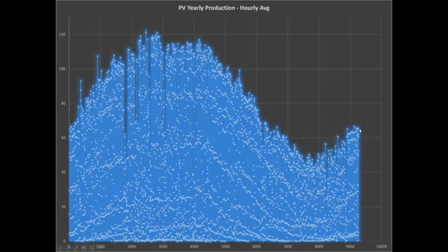If I trend the line between the two, I should not see any degradation in performance because of aging, because this is only 1 year's worth of data, and the system has been in place for the last 2 years. But over time, you will see that from month to month, it may not return to the exact same levels, and that's just degradation of the material itself. The other factor, in case it does not return to the same level, could be simple dirt on the panels, and typical practice is to clean them every 3 to 6 months, 6 months preferably, a complete cleaning to make sure they're operating at optimal efficiency.